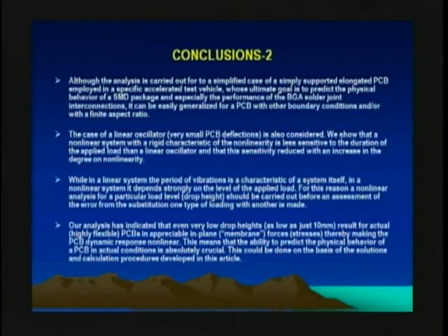The case of a linear oscillator, very small printed circuit board deflections, is also considered, and we show that a nonlinear system with a rigid characteristic of nonlinearity is less sensitive to the duration of the applied load than a linear oscillator, and that this sensitivity reduces with the increase in the degree of nonlinearity.